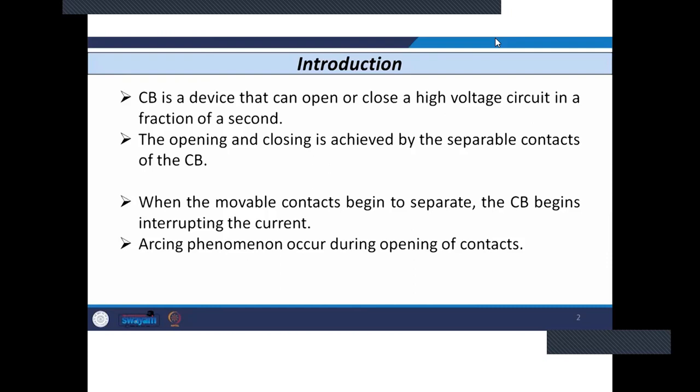For example, despite opening the contacts, it may remain closed and welded inside. From the outer side we will observe that it is open, but in fact it will be closed. So the arcing phenomenon may deceive the viewers and operators this way.